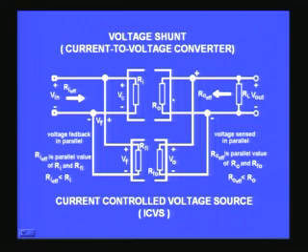The effect of the output resistance being reduced is to make sure that the output becomes much closer to a voltage source. So it becomes a voltage output and it is a voltage source reasonably. On the input side, the resistance is reduced, which means the input is not a voltage drive, but a current drive. Only when the current drive is connected to a very small resistance, the current cannot change significantly in the circuit, and therefore it will be very useful to introduce a current at the input side. So what you have at the input is a current, because the input resistance is very small, and what you get at the output is a voltage, because the output resistance is very small.